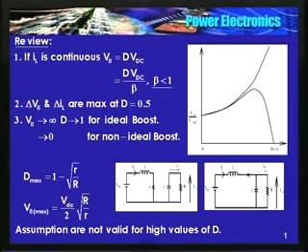Generally the thumb rule is that V0 divided by VDC could be of the order of 7 to 10. I told you how to design and fabricate a good inductor, using litz wire or a large number of thin conductors twisted together and using a ferrite core. In the process, the quality factor Q of the inductor improves. So if I use a good quality inductor, the maximum value of V0 to VDC could be of the order of 7 to 10.